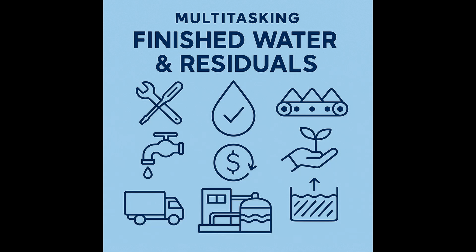The downsides? BFPs tend to be more labor-intensive. They require a lot of operator attention for monitoring, and especially cleaning, those belts need frequent watching. Because they're open, they can have issues with odors and splashing, making housekeeping important. They also often require relatively high polymer doses to work effectively, and the belts themselves are wear items that need periodic replacement. So, three main options, each with its own trade-offs in cost, performance, and operations.